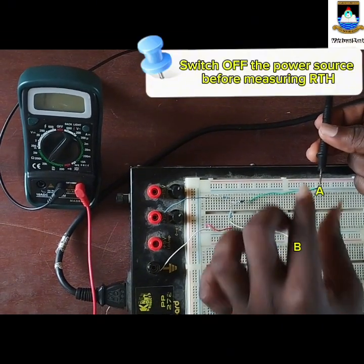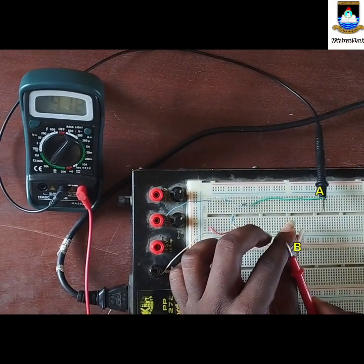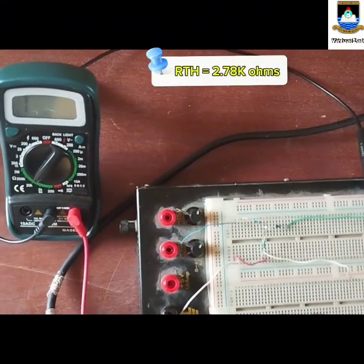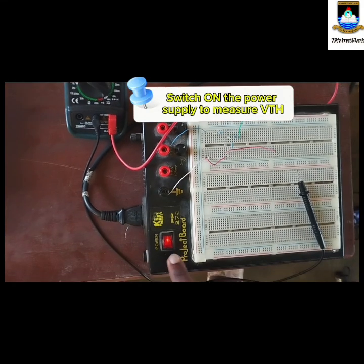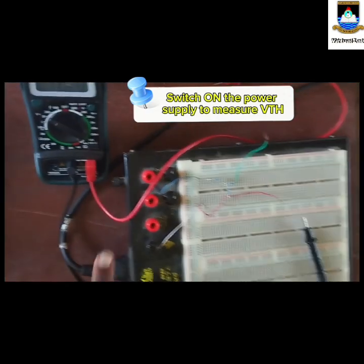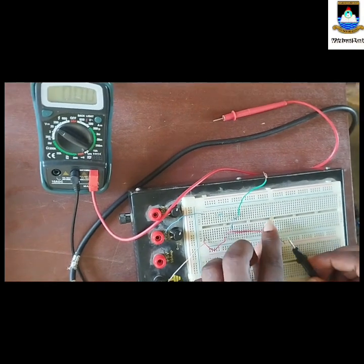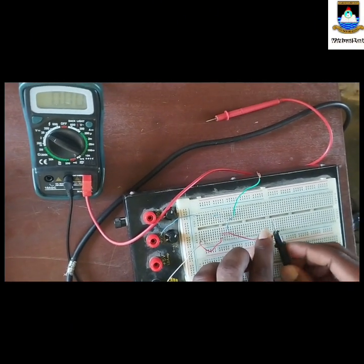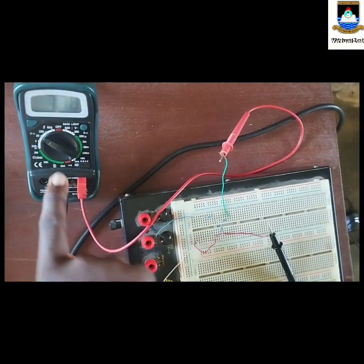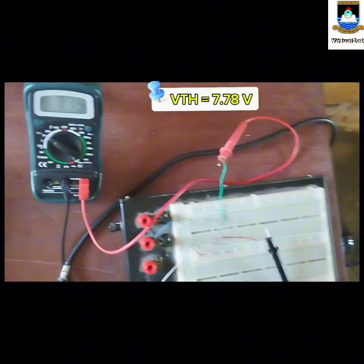Before taking the resistance measurement, make sure you switch off the power source, and let's measure the equivalent resistance from the two terminals. So we have 2.78, so that is our Rth. Then we switch on our power supply when taking our equivalent voltage, which is the Vth, and we measure across our terminals, terminals A and B. So adjust your multimeter to the DC voltage range and let's measure. So we have 7.78, so that is our Vth.